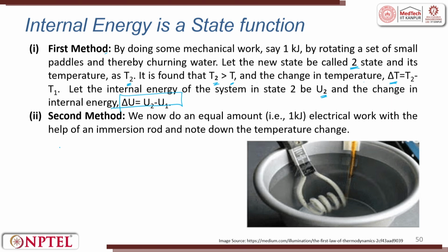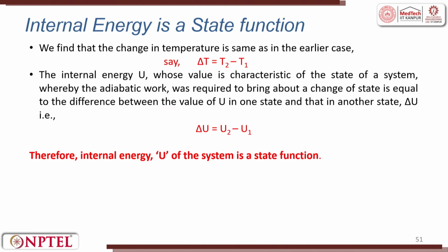The second method is we now do an equal amount of electrical work with the immersion rod and note the temperature change. So, you push an immersion rod in and heat the water. Now the temperature of the water goes higher. We find that the change in the temperature is the same as the earlier case, T2 minus T1.